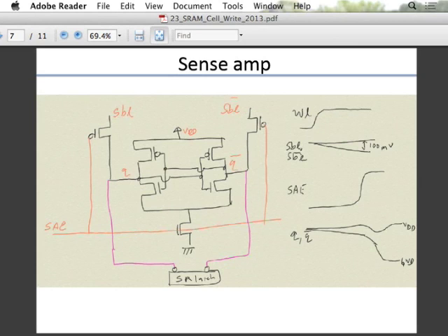And you see it's a self-fulfilling thing. Because he sees a larger voltage, this Q will reduce more rapidly than this Q bar. This is basically positive feedback. You already started off with Q less than Q bar, but because of that condition, Q starts falling faster than the Q bar, and that's what basically happens. This is the positive feedback.